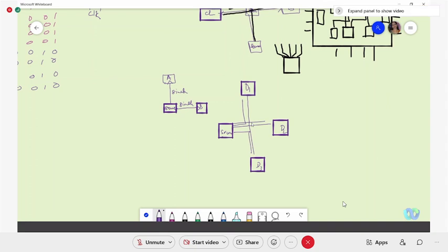Two remedies we are saying: all the signals should be of the same edge trigger. That is one remedy. The next one is that even if you are using the same positive edge trigger or negative edge trigger, if the wire lengths are not the same, then also there will be a skew. So place the source at a central position, or at a distance that is common to all the devices.